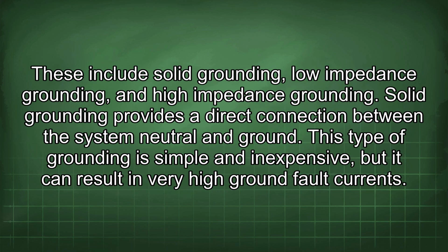These include solid grounding, low impedance grounding, and high impedance grounding. Solid grounding provides a direct connection between the system neutral and ground. This type of grounding is simple and inexpensive, but it can result in very high ground fault currents.